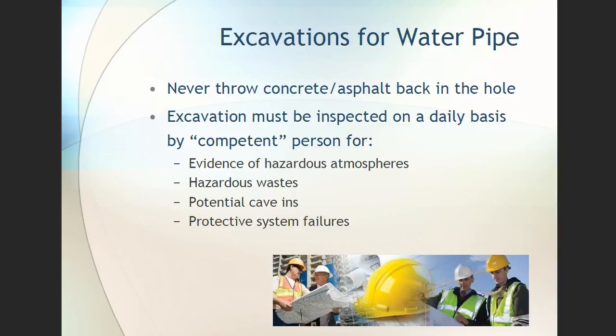So excavation must be inspected on a daily basis by a competent person. What's a competent person? Well, technically it's an OSHA certification, although there's a lot of job sites that don't have a specific competent person. And when there's not a certified competent person, who's the competent person? Somebody's got to be in charge. A boss. You can't have 5 guys and gals go out there working on a project with nobody who's creating leadership. So again, that competent person is looking out for the safety, and they're looking for atmospheric conditions, hazardous waste, potential cave-ins, protective system failures. It's a safety issue.